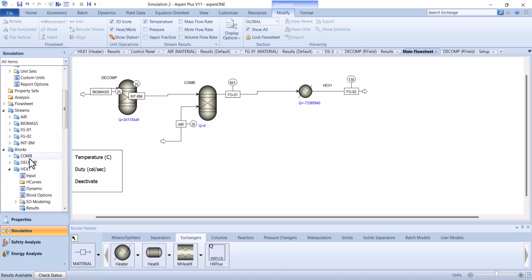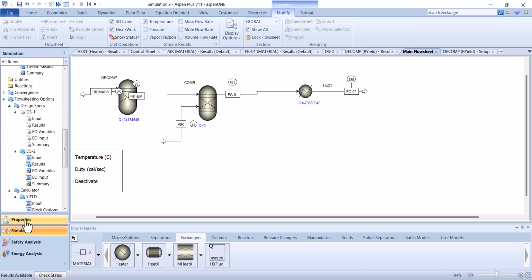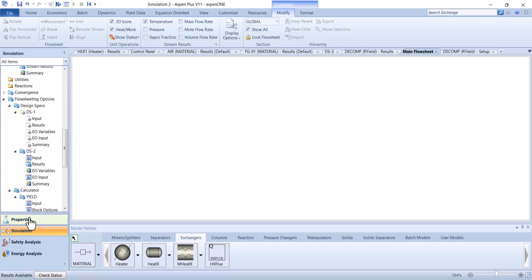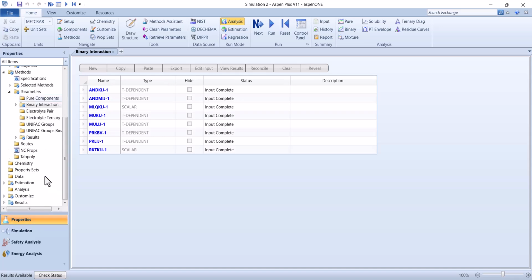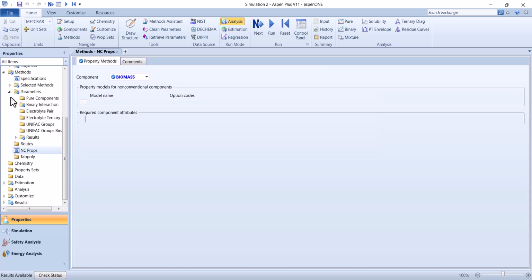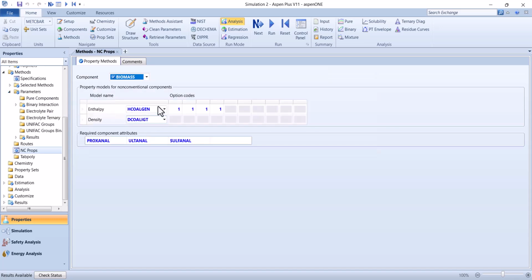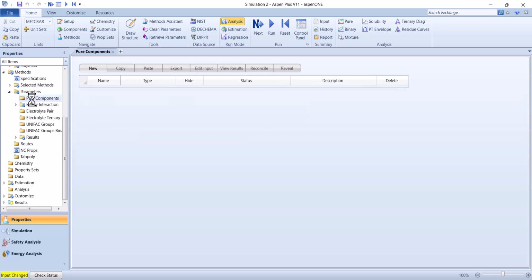Accordingly, and you can mention it is based on the amount of heating value which has been calculated by Aspen, but you can change the heating value manually also. There you need to mention for enthalpy instead of 1.6 there, and then you need to go to the pure components,